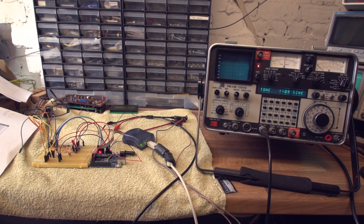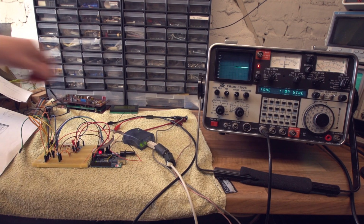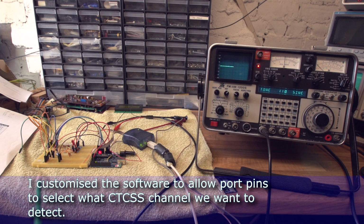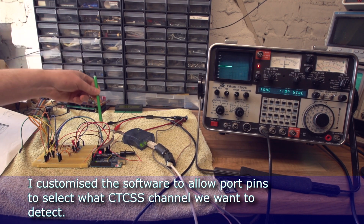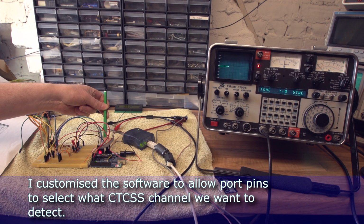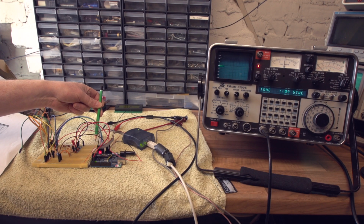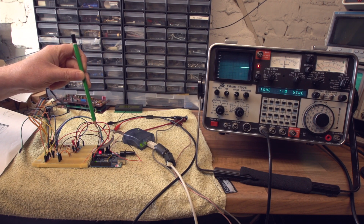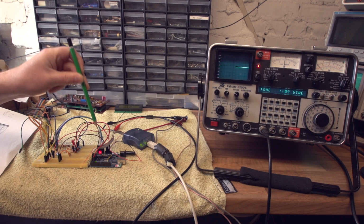Changed the software for the Arduino to allow basically removal of the display. The LCD has now been removed. We basically have a binary select port now, where you can set bits 1 to 6, and that allows the program to select which CTCSS tone you want to detect.